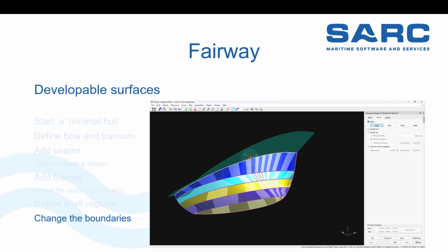But we have more developable plate types. One is in one direction, for example a center line and an inclined frame. If the angles are identical everywhere, then the plate is developable. Or if it's completely flat, or a cone would also be developable. So you can use those shapes. I'd have chosen the most flexible one. But yeah, you can do that.